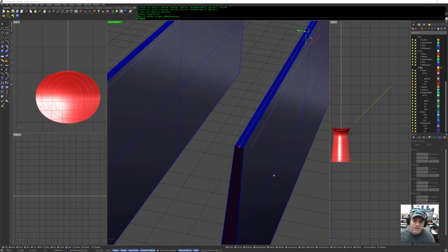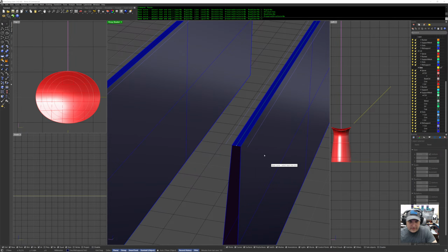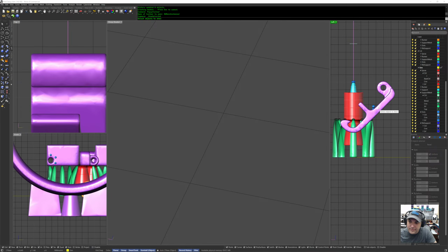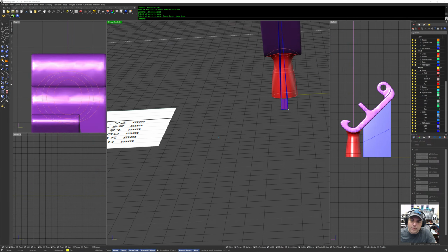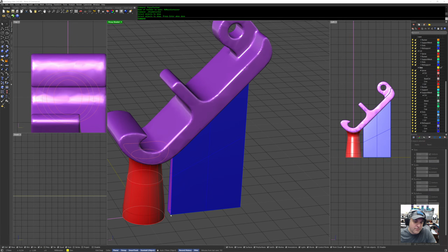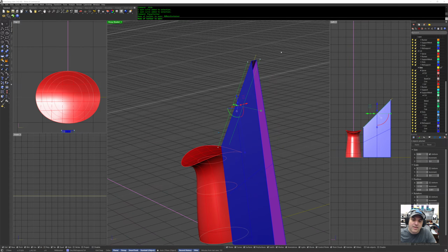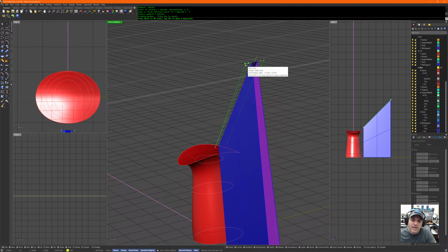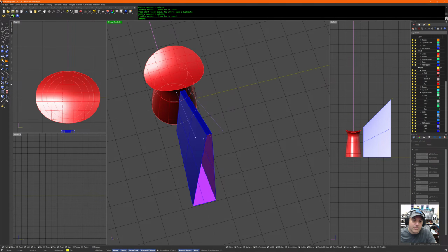I want to grab that junk curve and say flow stretch without copy from this curve to this curve. There we go. And we get the same thing. If I want it to be wider at the base, which it looks wide enough at the base on this side, but not this side, I can take these, turn points on, grab the 2 endpoints, break history, and just scale them out, and our wedge will get wider as it gets out to here, but it'll stay the same.